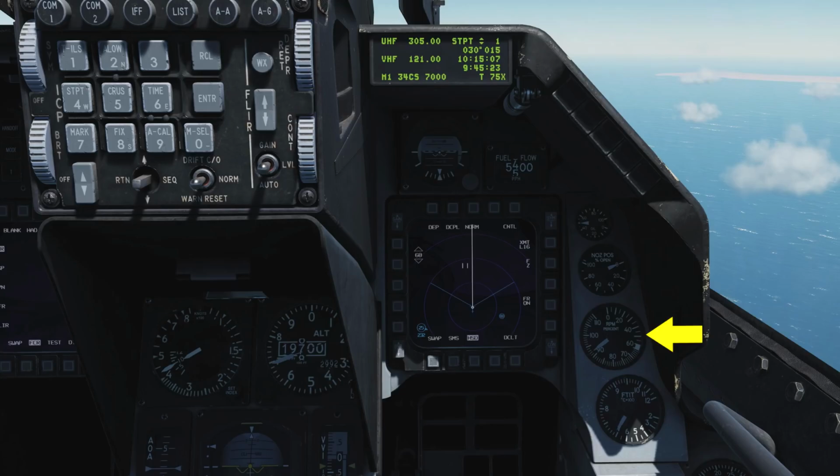The RPM indicator indicates engine RPM, is supplied by the engine alternator, and is expressed as a percentage value from 1 to 110. Note that the speakers still go to 11. The fan turbine inlet temperature, or FTIT, indicates the average temperature in degrees Celsius, and it can range from 200 to 1200 degrees in increments of 100.